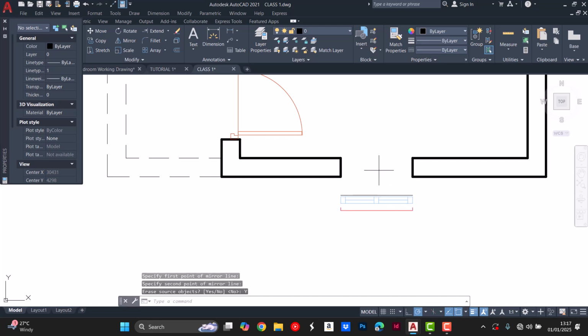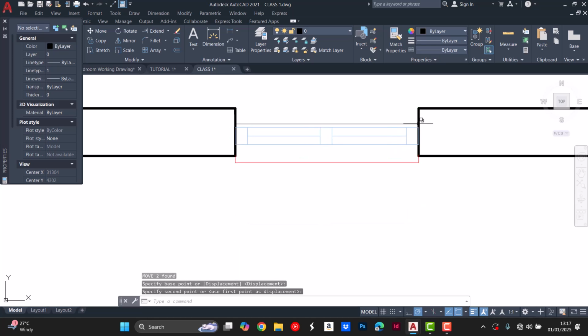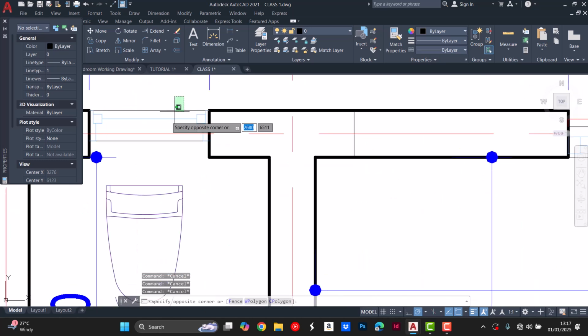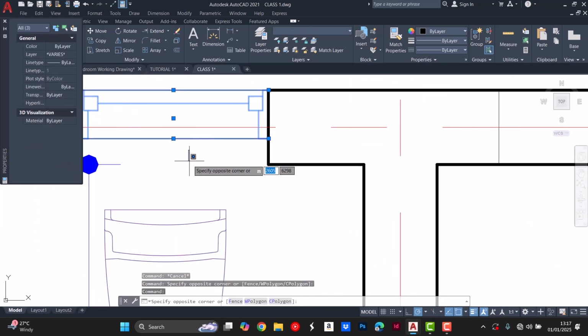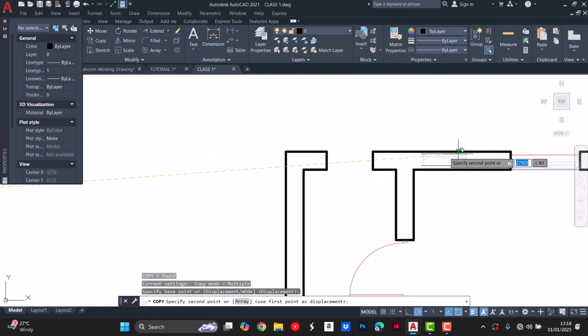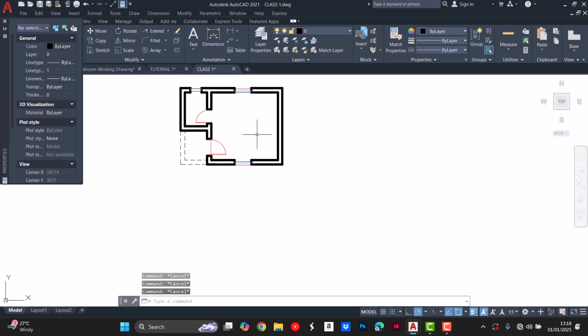So yeah, what I'm doing is mirror. I'm mirroring it. It's supposed to face this way. So I just mirror. Mirror is MI. Click on MI, be able to do that. So I click on this CO, then I click here, take it to this point, and I drop it. Okay, and I drop it.